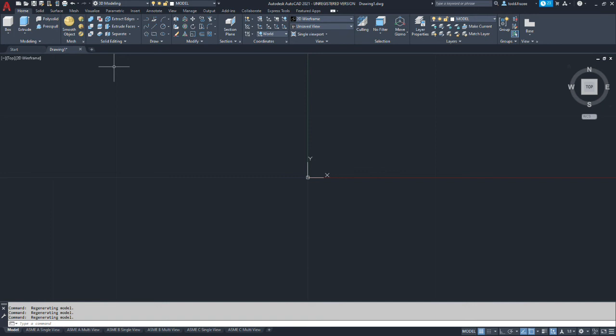Alright, so when I look at a part, I try to decide how to orientate the part such that I'm working in the world coordinate system with the correct view directions, and also place the origin in a place that makes sense for the part. I look at the function of this part, and the main function of this part is to hold a bearing, and we want to describe in our front view the most number of details as possible.